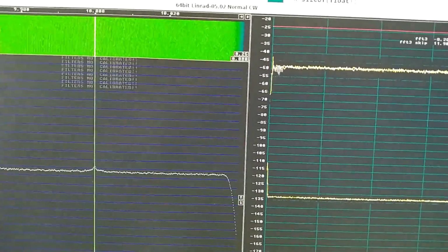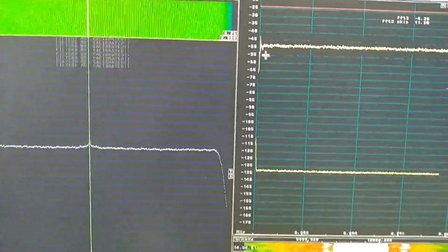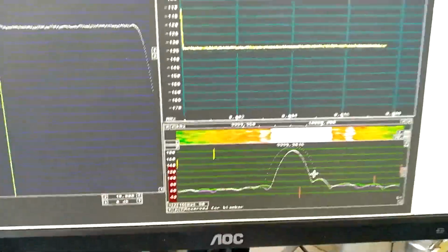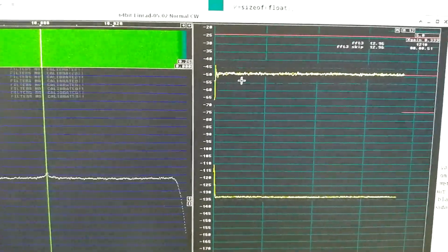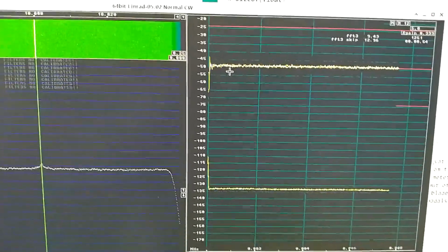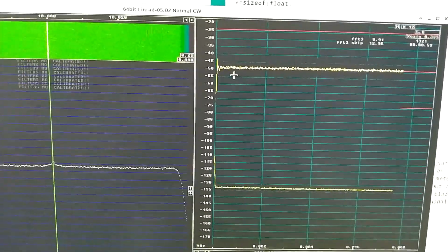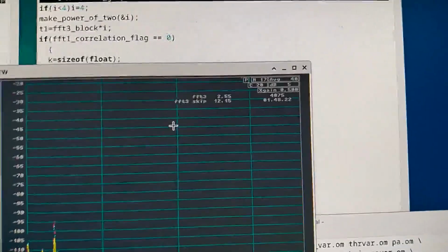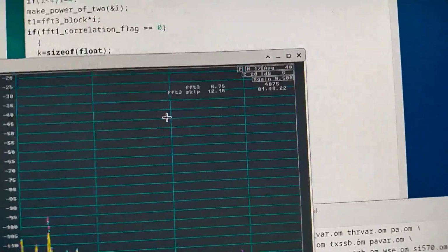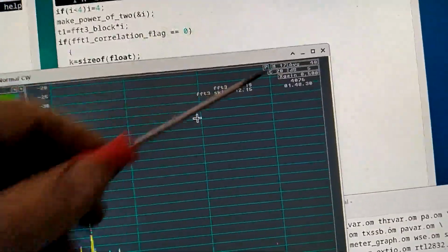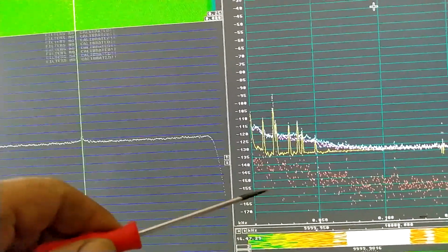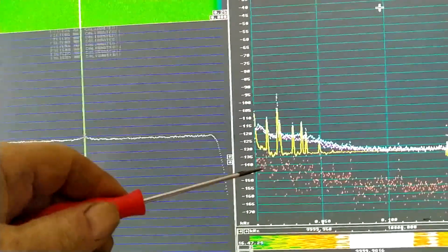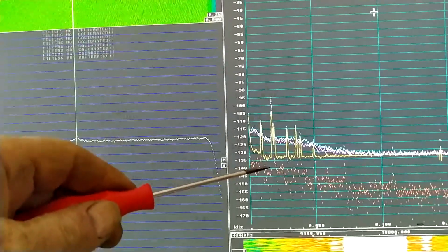And also to see that at very low frequencies there are artifacts because of the settings I'm using. I have a very high baseband sampling speed, and it doesn't work right for low frequencies. I have now set a very large transform size, 17 here, to be able to look at relatively close range despite the very high baseband sampling speed I have.